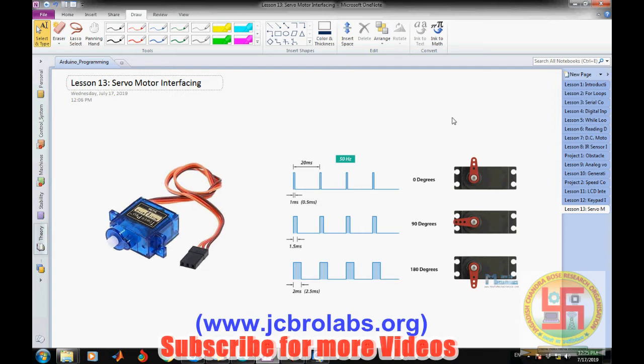Okay, so as we are seeing in this figure, this is our servo motor, which is generally available for toys application or for lower end application. Generally it has three wires, for VCC, ground, and the PWM wave. Generally there is a brown wire or a black wire, which is ground, and then another one is the red wire commonly used for plus 5 volt, and then the last wire is light yellow or white wire that is used for applying the PWM wave.